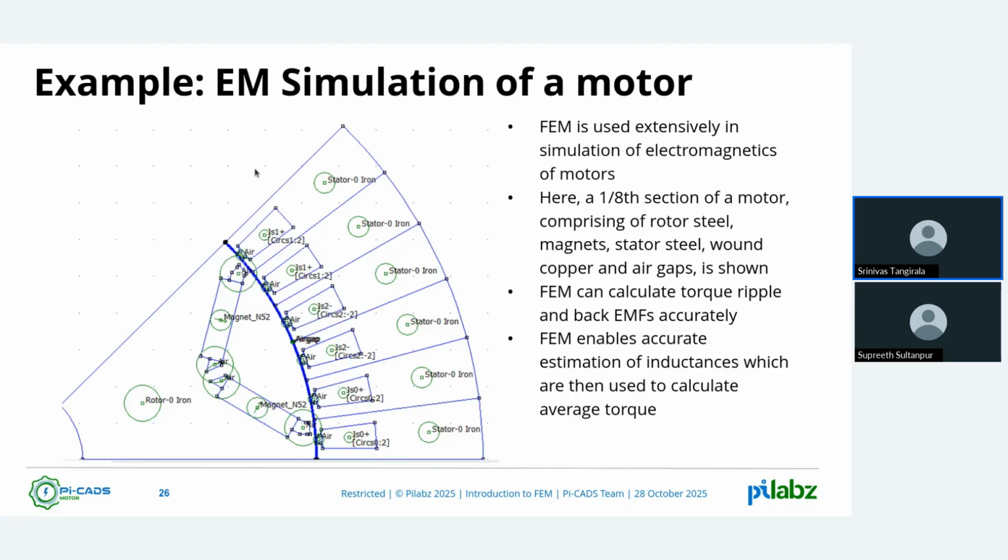Laminates meaning a thin plate, which is carved, they put holes in it, and that will become the stator. When you stack up about 50 or 100 of these laminates, you get a stator. Similarly for the rotor, you make a geometry of a laminate and then stack them up.